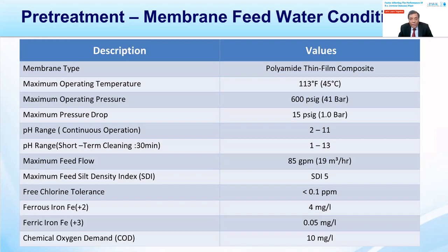But it is the job of your designer, who is proposing the system, to recommend the pH as per the composition of your raw water and recoveries, and you should be maintaining that condition. This guideline is basically for designers who can manage their system according to the limiting factors given for the membranes.